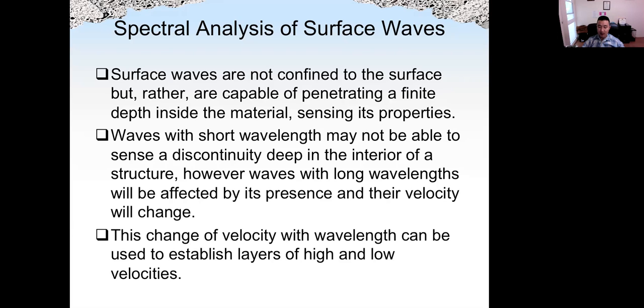Waves with longer wavelengths can penetrate deeper, but the resolution is not as high as with short wavelengths. We can use the velocity at different wavelengths to establish the layers of high and low velocities. So this is the spectral analysis based on the Rayleigh wave, or the surface wave.